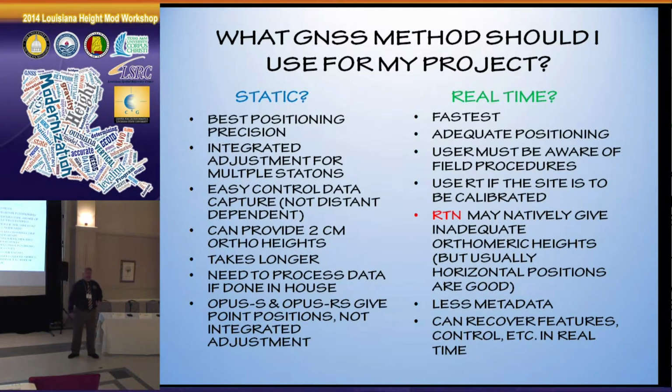So static or real time? Well, of course, static is a lot more, not a lot more accurate, but it is more accurate than real-time positioning. It's more adjustable. You can process the data a number of different ways. You have longer occupations so that you can deal with cyclical multipath. You can try different cutoff angles. You can do different things with static data you can't do with real-time.